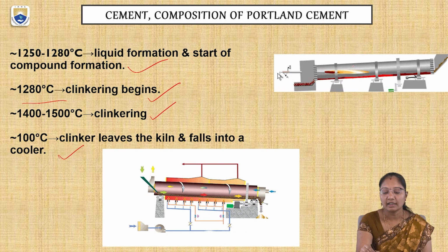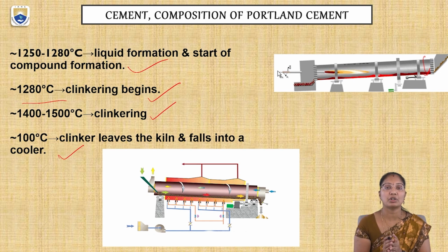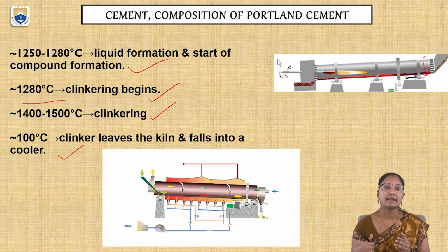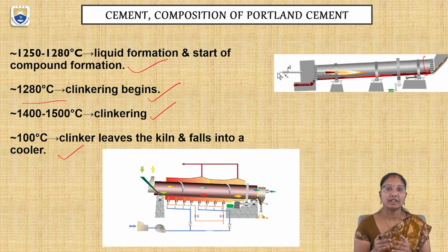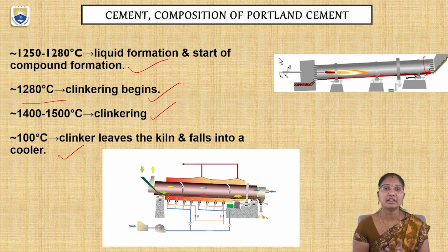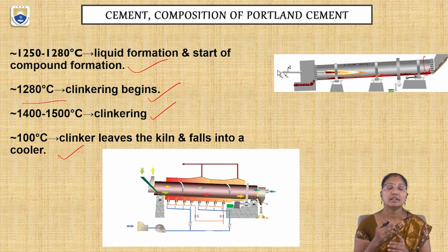Here we can see the sintering at high temperature, and the kiln is rotating. As temperature proceeds, we can see the color change, maroon and red, meaning as the temperature proceeds, it loses its water molecules around 300 to 350 degrees centigrade. From 350 to 650 to 900 degrees centigrade, only iron, silicates, aluminates, calcium oxide and magnesium oxide remain, converted from the calcium carbonates and magnesium carbonates, and carbon dioxide traces evaporate. Then it has a pure mixture.